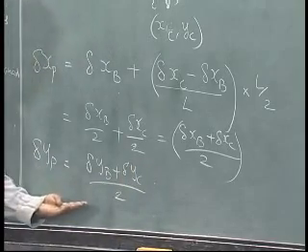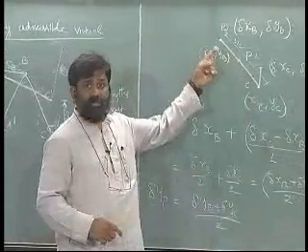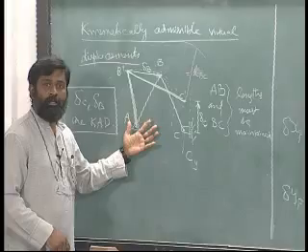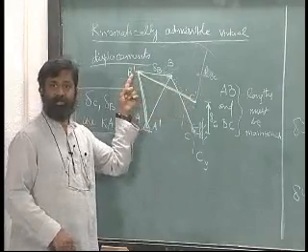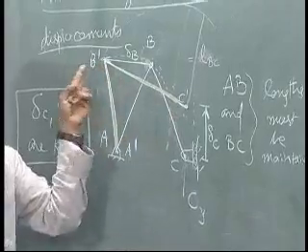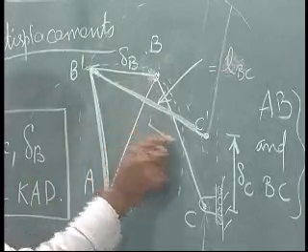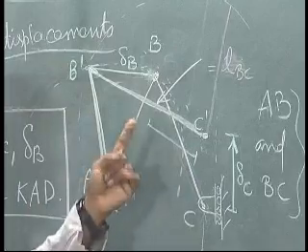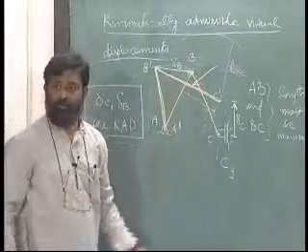The reason why I am telling you this is it may be worth finding out the displacements of the ends of these bars. Once I find out the end virtual displacements, it is possible to find out at any point in between. So if there is a force acting here like this, and I know this length with respect to the total length, it is very simple to find out the virtual displacement at this point, and I can use that for this active force.